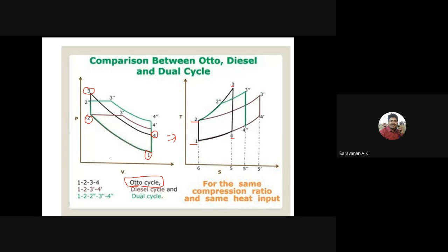And for the same, what is the diesel cycle? Here the compression ratio is the same. We are comparing these three cycles for the same heat input and the same compression ratio. The compression process 1 to 2 is always the same for all the cycles, so we can't change it.